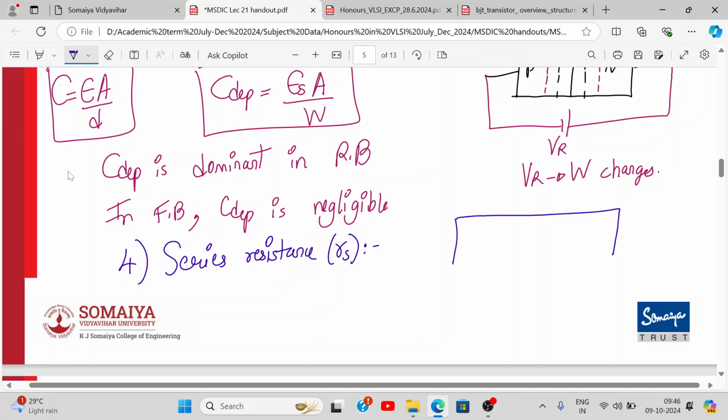Okay. So in this PN junction, if this is my depletion layer, what is this? N and P. This is N neutral, P neutral. Why do we call them neutral regions? Because the fields are not present over here. Yes or no? But these regions are also made up of semiconductor. They will have resistance. So there will be resistance over here, in the entire region. Got it? And that combined resistance we call R_S. Understood?